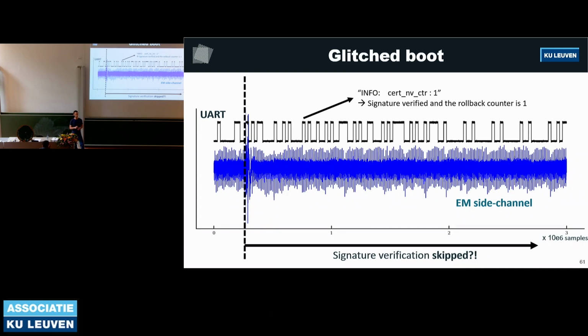And since we can do this, it means that we can modify the second stage firmware that's on the external eMMC. That means we can also disable all of the other signature checks that that stage would do, and so on. So from this point onwards, we have a complete compromise of the terminal, and we can execute whatever code we want, even from the very early boot stages.